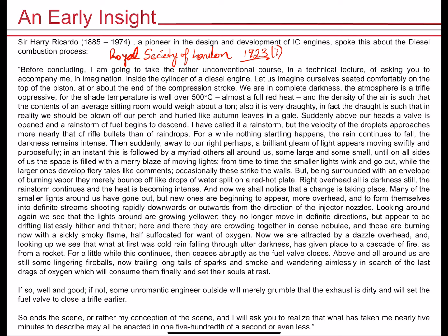Occasionally, these strike the walls. But being surrounded with an envelope of burning vapor, they merely bounce off like drops of water spilt on a red-hot plate. Right overhead, all is darkness still. The rainstorm continues, and the heat is becoming intense. So what did we just describe there? We described start of injection, ignition delay, and premixed combustion.